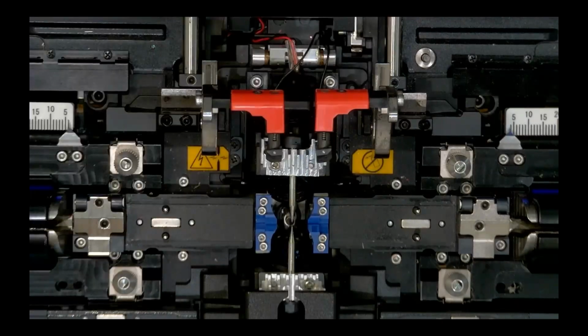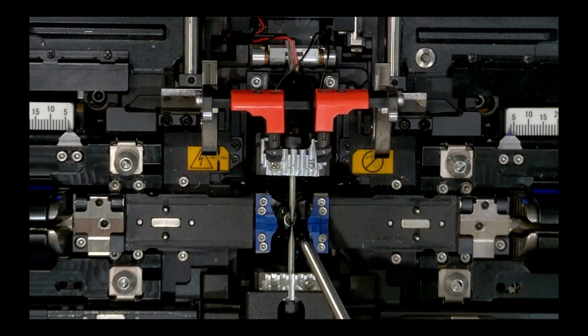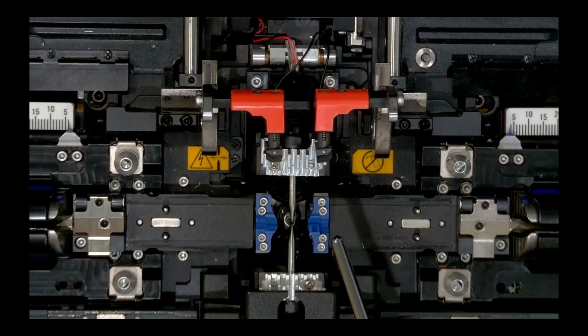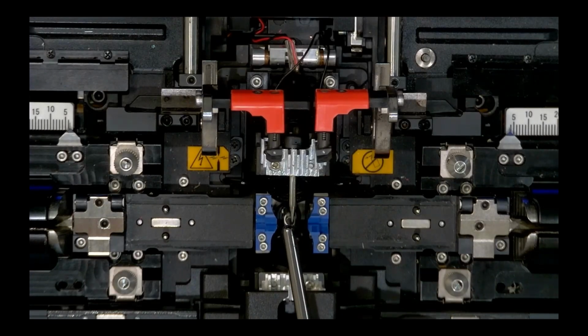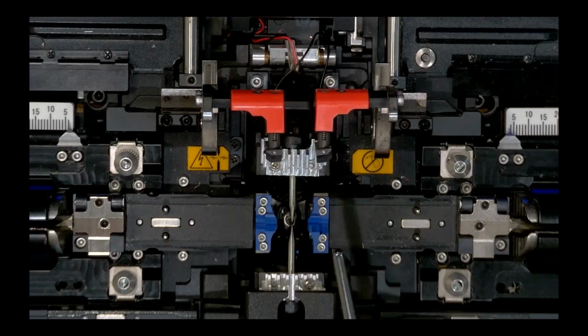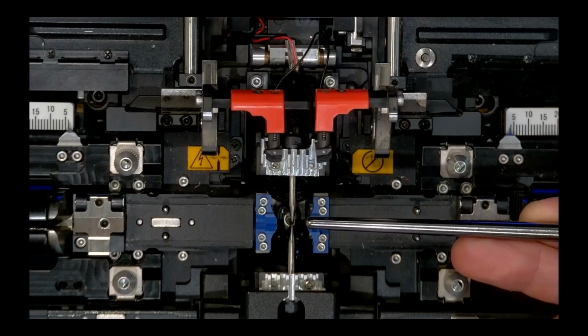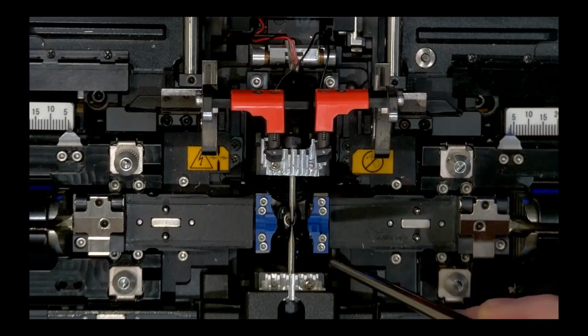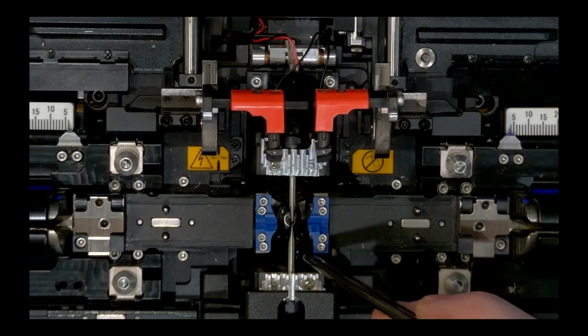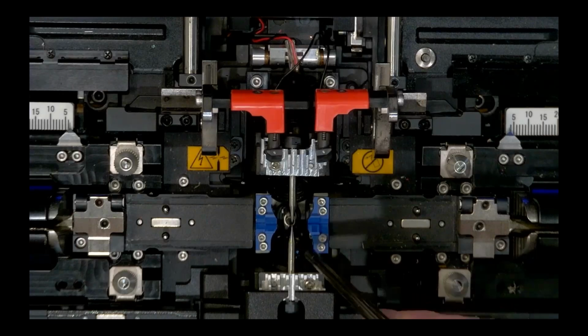All right, and while we're focused here in the middle, the next thing you'll see is a unique feature of the plus models. Below the electrodes, you can see there's a little circle here, and that circle is actually a periscope mirror. When you are using an end view capability, that mirror will move up between the electrodes and allow the fiber's end face image to be reflected through that mirror and down into one of the cameras, which are right here on either side below the electrodes. You may be able to see it.